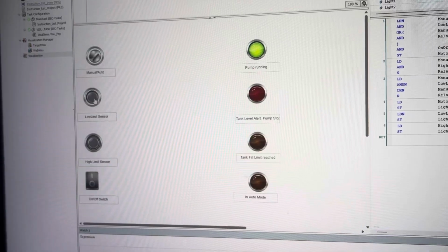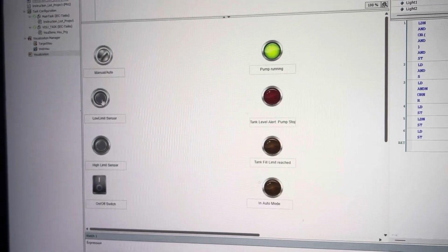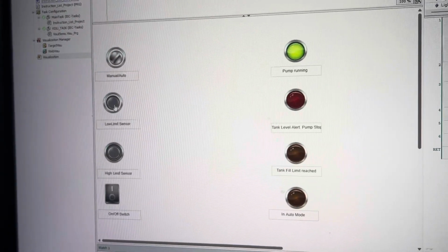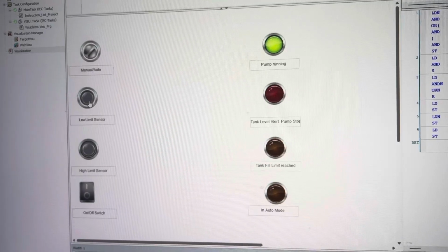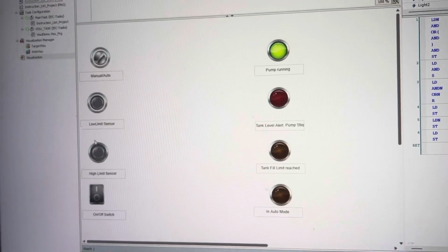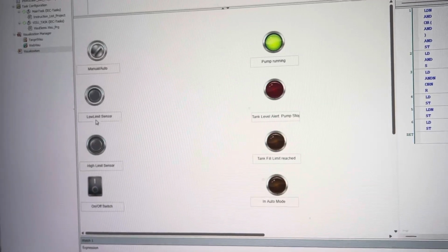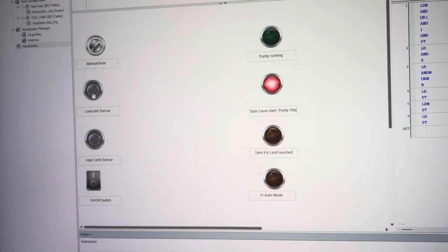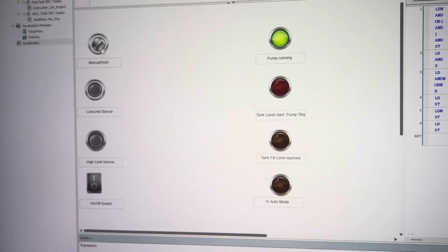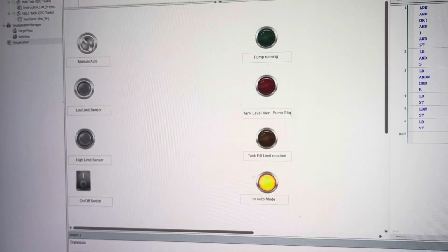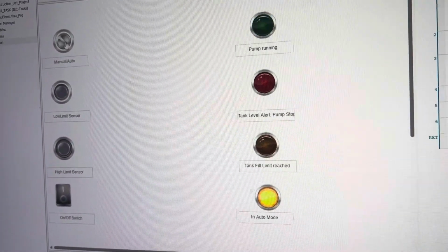And that will run until the low limit switch sensor stops detecting that the liquid level is low. And that will keep on going until you go to your high level, and run again until it's empty, and stop and restart it in auto mode. And then you can actually stop it by using the manual controls. You can either turn on or turn off the pump.